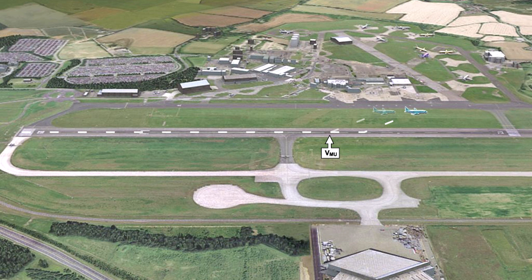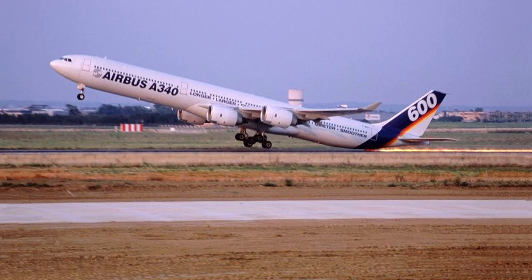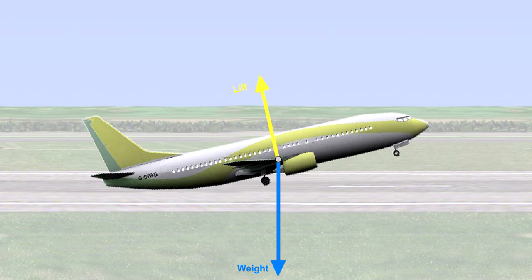The reason is because VMU is very close to the stall speed, and the aeroplane controllability is very sloppy. And lastly, in order to actually lift off at VMU, some fairly dramatic actions take place, which may be uncomfortable for the passengers, as shown by the image on the screen. It may seem strange, but the aeroplane is actually able to lift off at a speed where lift is less than weight. The reason being because so long as the nose can be raised to a high enough attitude, then there is a vertical component of thrust, which, together with lift, balances weight.